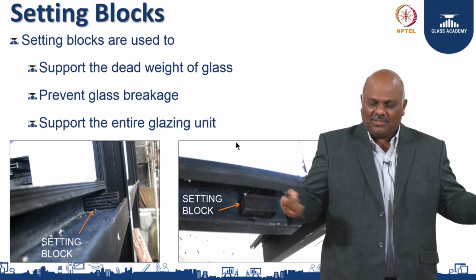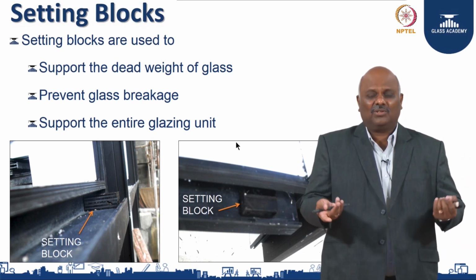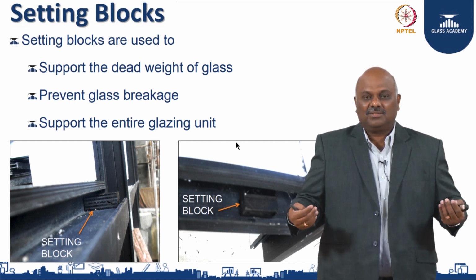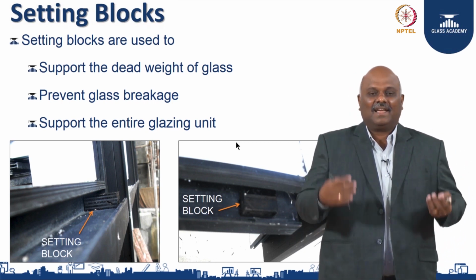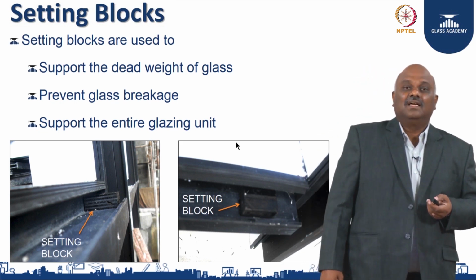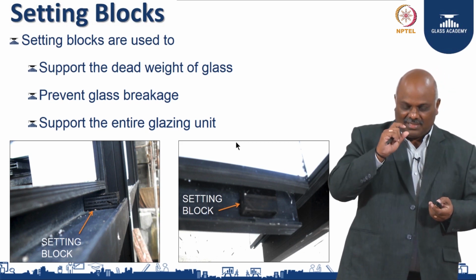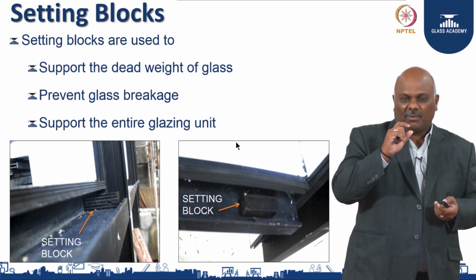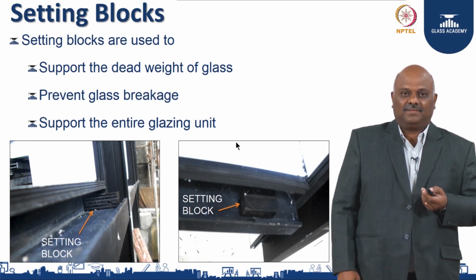Otherwise, if you put a glass without a setting block, what will happen? The load will not be distributed equally, and then things will start cracking and the whole thing will go for a toss. So, setting block design is very critical, and also the hardness. It can be too hard, it can be too soft. It has to be designed with a proper Shore hardness, so that you will be able to take the load.